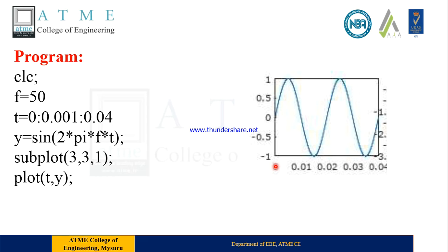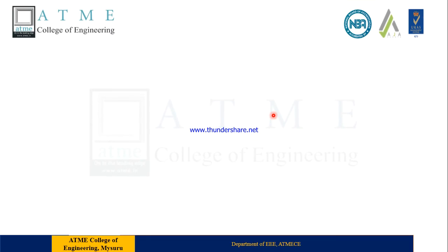Here we can see the time period being 0 to 0.04, with steps of 0.01, or you can also have any intervals of sampling that we desire. You can check out how it is performing as well. So now I have a continuous input signal. Now I want to sample it so that I can reconstruct it back to its original form after conversion from A to D and again back from D to A.